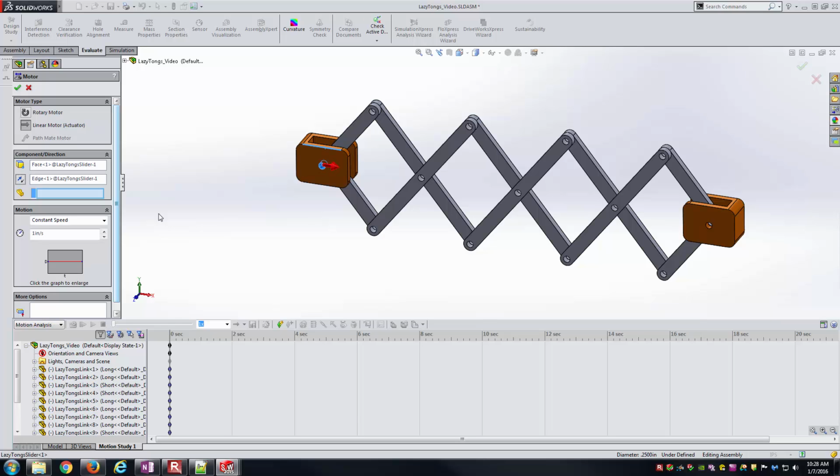An example of where you'd want to apply that to is if you have a hydraulic cylinder. Think of the kind of backhoes or heavy equipment you see in construction environments. Some of those cylinders are extending as well as rotating at the same time. When you have that kind of motion and you're applying the motor to the actual piston and rod assembly of the cylinder itself, you want it to be able to say, hey, move this relative to the body of the cylinder, so that you have the correct motion going on. In this case, I don't have that kind of interaction, so I don't have to worry about it.